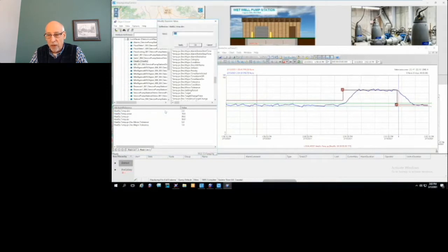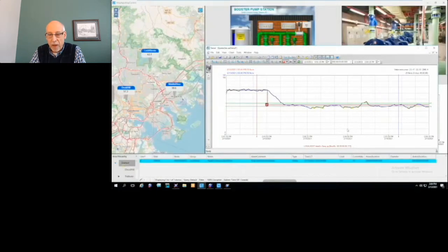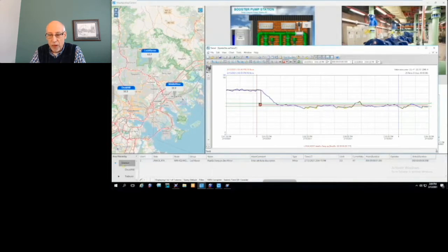So right now you can see that it did. Those trend controls in yellow meant that the process variable skewed beyond the actual set point, and it generated that minor deviation, because that's the amount of deviation we specified in that simulator. So great use case to be able to track when we start going out of control from our set point.